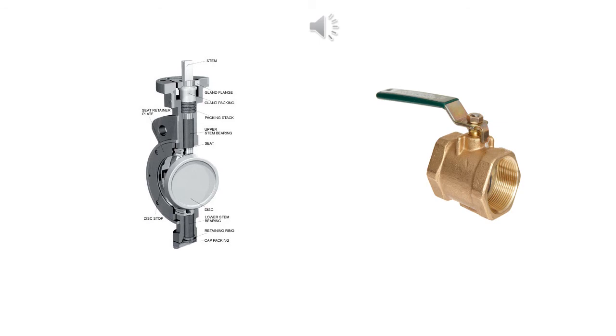Some advantages of butterfly valves are the compact design requires considerably less space compared to other valves. They're light in weight. The quick operation requires less time to open or close. Some disadvantages are throttling service is limited to low differential pressure. Disc movement is unguided and can be affected by flow turbulence.